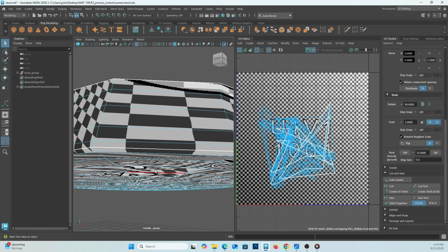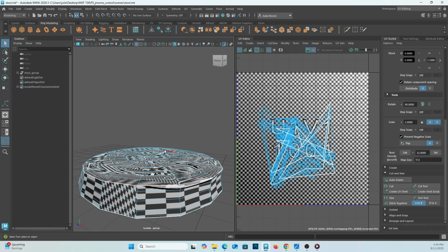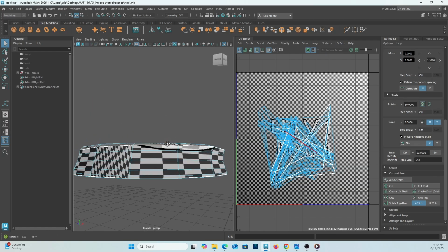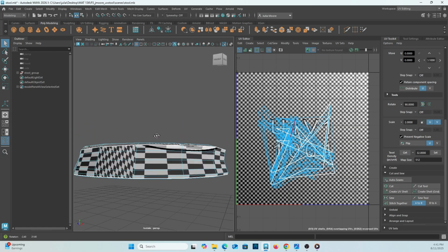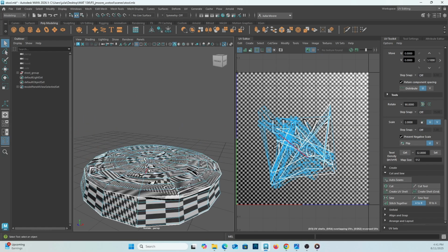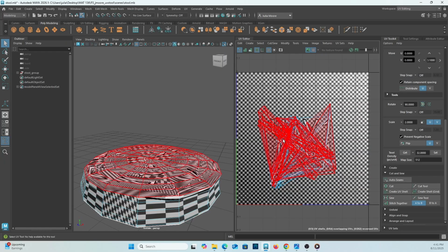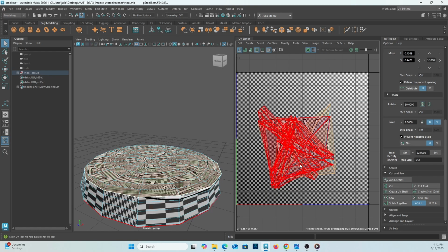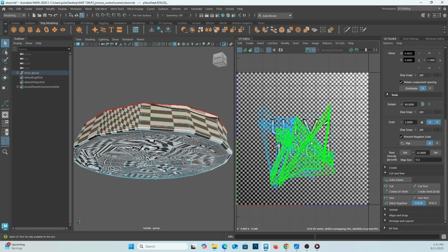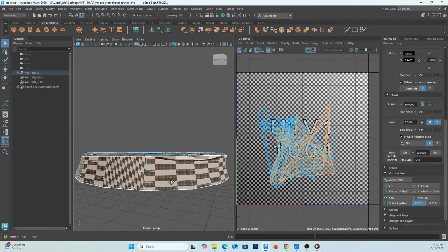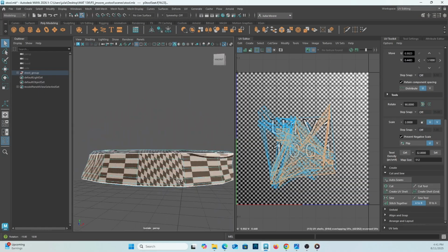So what did that do? Did I cut the entire model in those spots? No, I just cut the actual UV map projection in those spots. So if I go to object mode, and then in the UV editor, I go to UV shell, you can now see that those 3 parts of the UV projection are now separated from each other into 3 different UV maps. So that's how you cut to make the seams and to control where your seams are.